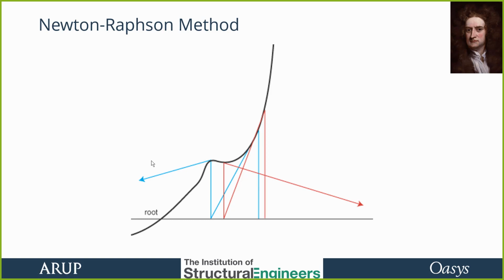These slopes, either for equations or real structures, are not always smooth. If you remember the design space image from earlier, and sometimes if you start off with two starting points which are close together, due to the complexity of the slope, they can suddenly diverge and give you very different answers. Now, Newton-Raphson is a non-linear analysis option, and it can be very quick, or it can be terribly slow, depending on the structure and where the starting point of the analysis was.